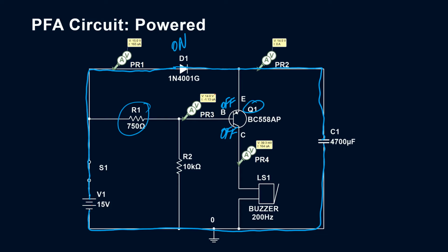So that's something that we had to work on to make sure we knew what R1's value needed to be to keep the buzzer from sounding under power. You'll see on our project that we'll show later in the video that there is a potentiometer in place of R1, and we use that to demonstrate the variable resistance to determine what resistor we needed in our actual circuit.